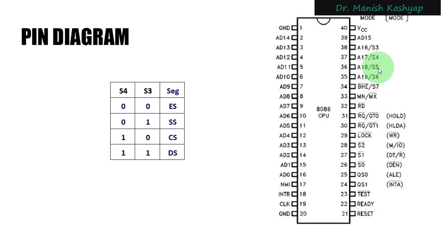If this pin has a high value, then that can be treated as the interrupt enable flag being on. And if it has a low value, that flag is disabled. That flag is especially used for maskable interrupts, the interrupts whose servicing you can deny. So this pin is being used to indicate the status of that.